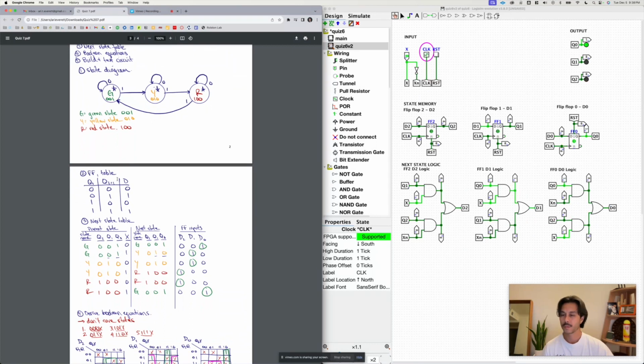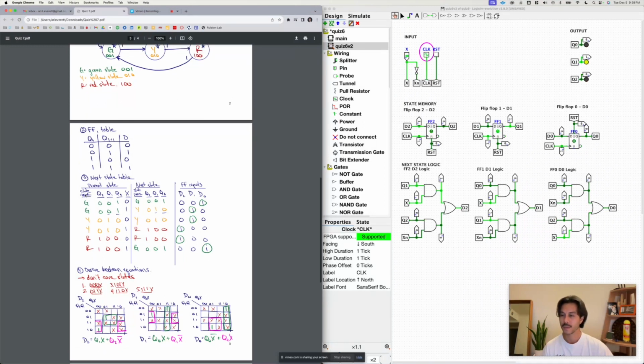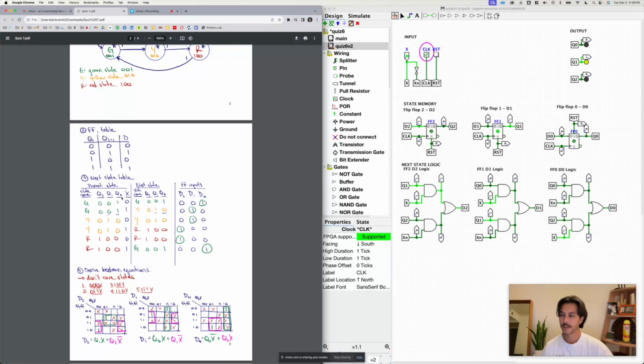In our flip-flop table, the constraints are to use the D flip-flop, and here's how the transition table looks for D flip-flop. Next state table is the present state, next state, and then the flip-flop inputs to get from present state to next state. The green has 2 different inputs with X here. X is noted by these lines right here from the state diagram. 1 will push us forward in the process, 0 will stay put. So since there is 0 and 1, each state code has 2 states that it could be in. And 0 it will stay, and then 1 it will go to next.